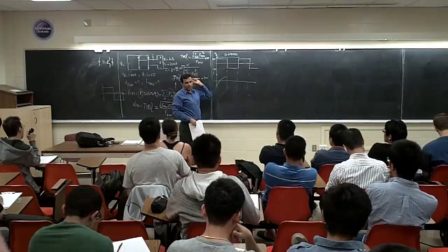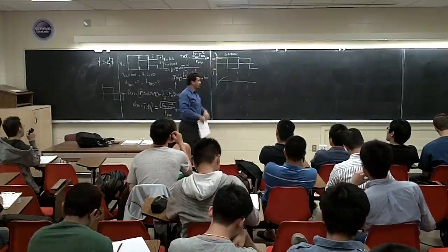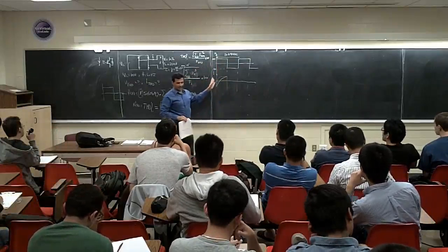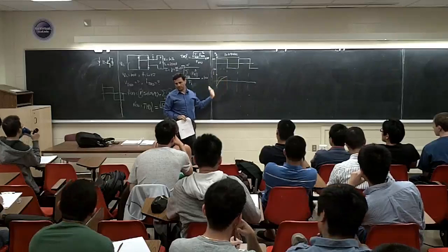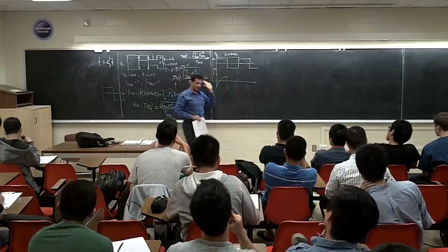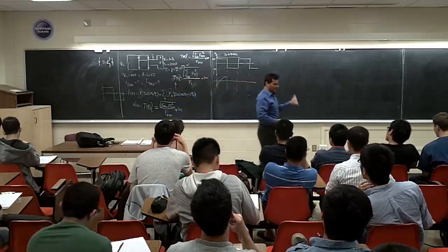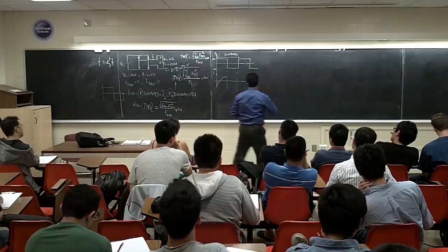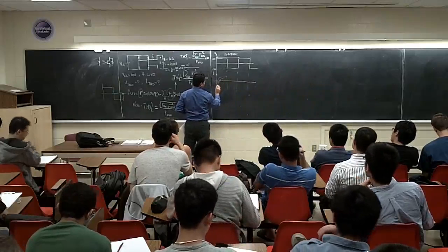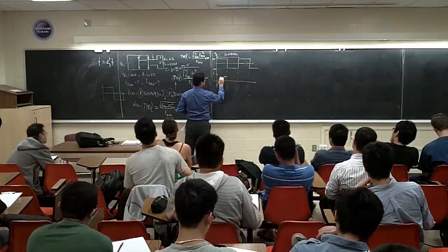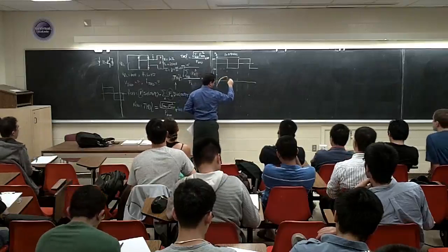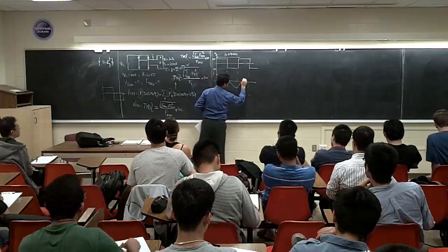A little bit more. If it was 8 times, when I plot this one, I said it's going to be like this, right? Because it's more than 4 times of the time constant. System is going to get to the stable side. For the DC circuit, we said if you are more than 5 times of the time constant, you are in a steady state. Basically, the waveform is going to be like this. But in this case, because it's almost 3 times, I'm guessing it's going to be something like this. And here again, it's going to go like this and like this.